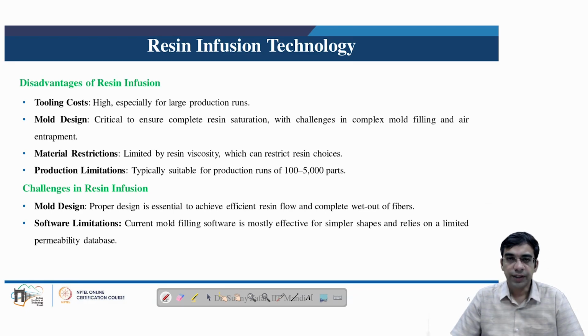The resin infusion technology also has certain limitations which can be addressed. These limitations include tooling cost. These are especially high because the mold which is used may need to be quite robust and have a good surface finish. So expensive materials like tool steels etc. can be used to develop such tooling, and the cost may be higher for intricate or complex designs.